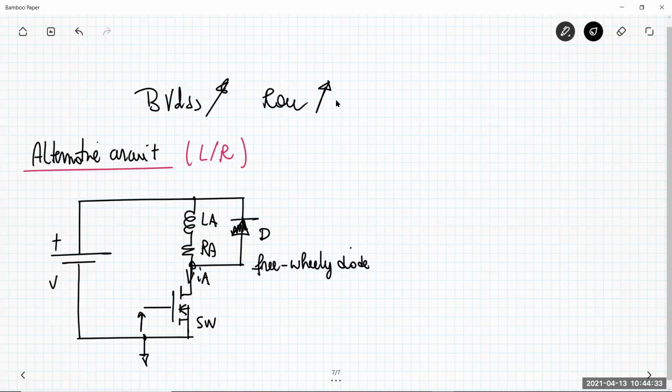And so when the MOSFET is conducting the current, this node here, the drain, is basically short-circuited to the 0 volts, the reference node. While this node here is at the supply voltage V+, so the diode is off. So during the turn on, D is off.